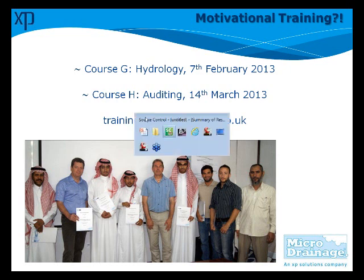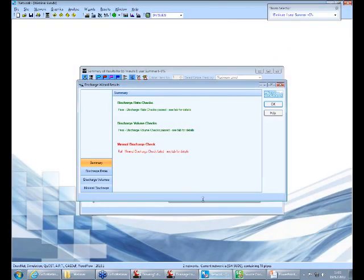Okay, I'll go back to the program now and let's have a look at the final results. I'll just wait for the screen to refresh for you, and there we are. So the summary results from the Discharge Wizard are now being displayed, and we've got 3 different things that we've checked for here: the Greenfield discharge rates, the Greenfield discharge volume, and the minimal discharge check, that first 5 millimeters of runoff, the first flush, that highly polluted runoff.